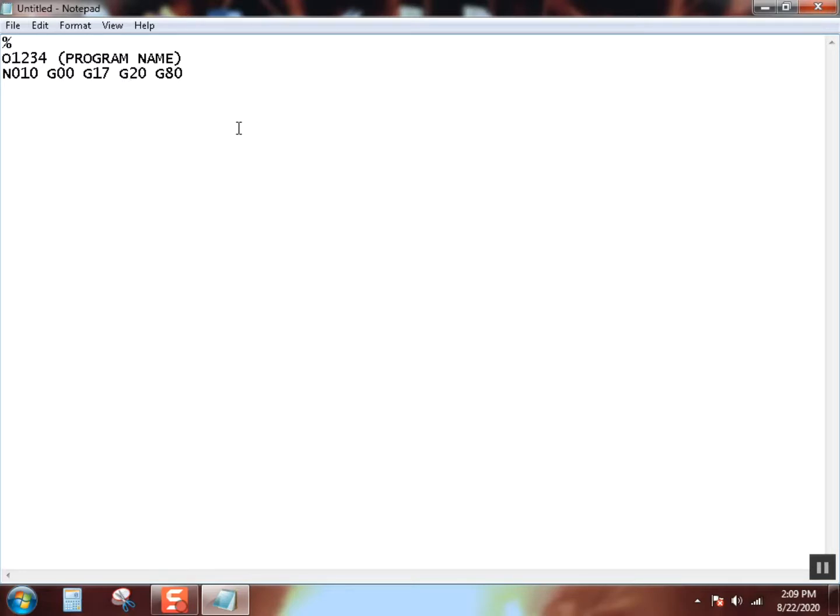Next thing is G90. G90 means we're going to use absolute coordinates. That means everything is coming from X0, Y0. At that particular point, that doesn't look like a bad one. The only other thing I'm going to put in there is a G40. Now, if I was going to put a G40, I probably should put it right here to keep our... Again, the machine doesn't care. Got a space there. The machine doesn't care, but I do.